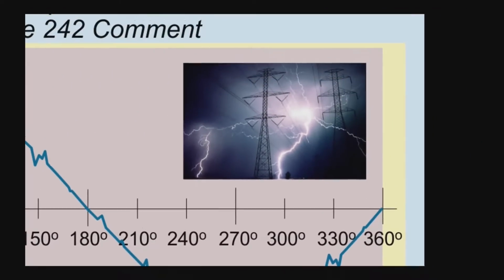Sure. Well, essentially, lightning or switching transients on the utility can corrupt the sinusoidal voltage waveform, and it can cause very large spikes, just like it sounds. It's a very large overvoltage. So if you've got 120 volts RMS, you could have thousands of volts on top of that for a very, very, very short period of time, microseconds. So we see the little image right here, and I'll zoom in on it.